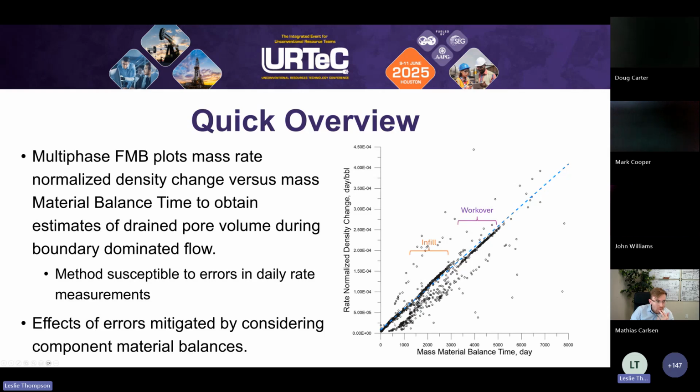So whatever they did on the workover, and I can't remember what it is right now, they somehow increased the completion efficiency. In my experience, and I left the industry 2 or 3 years ago when I retired, I found that very old wells that were not completed with as many fractures per foot had much higher intercepts and much longer transitions to boundary dominated flow.